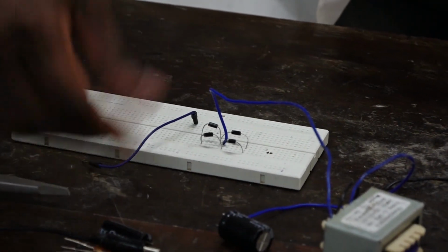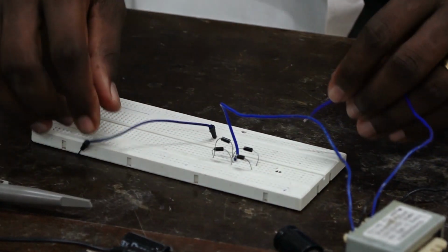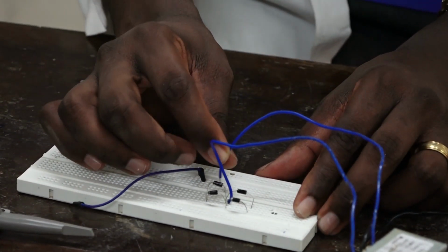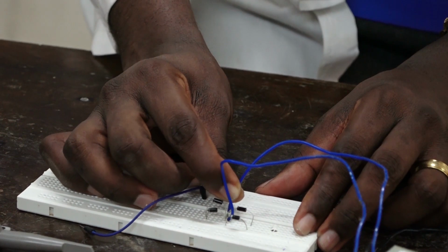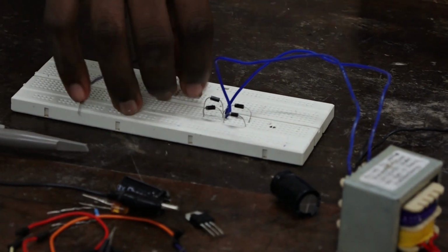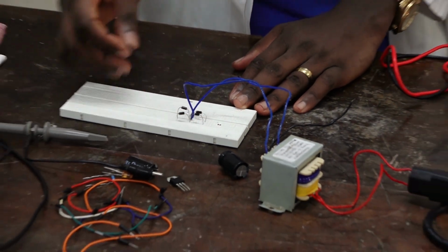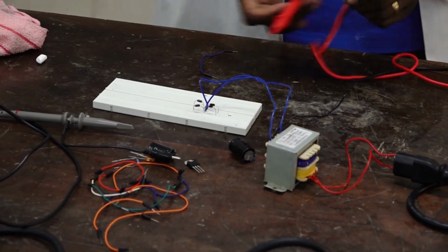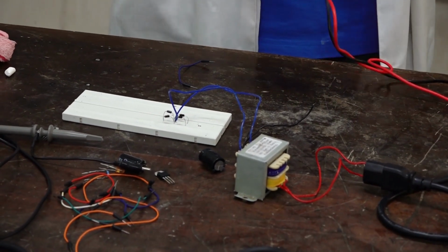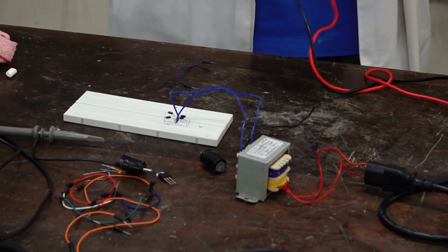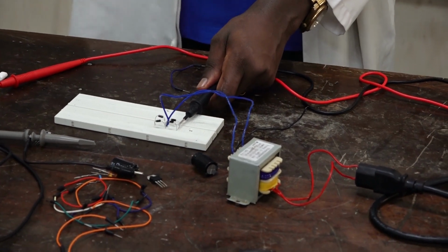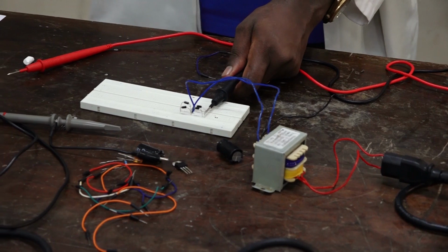Again, sometimes if you have a number of jumpers, you can just separate them. But let us just use it without using the number of jumpers. Let us assume that you are not given enough jumpers. So next, remember that. Look here, this is the common cathode, which we are going to call the positive terminal of the bridge rectifier. And this is the common anode.